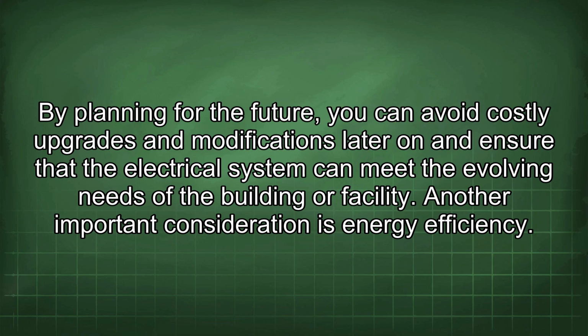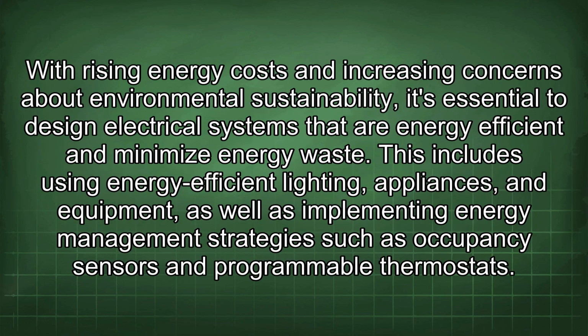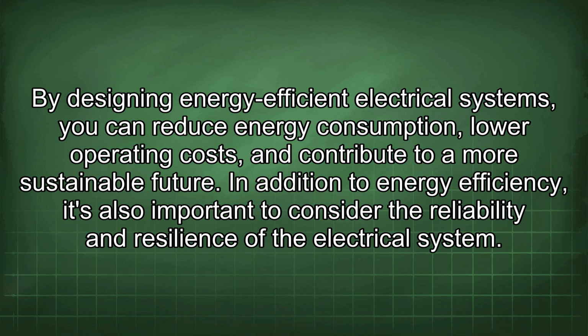Another important consideration is energy efficiency. With rising energy costs and increasing concerns about environmental sustainability, it's essential to design electrical systems that are energy efficient and minimize energy waste. This includes using energy-efficient lighting, appliances, and equipment, as well as implementing energy management strategies such as occupancy sensors and programmable thermostats. By designing energy-efficient electrical systems, you can reduce energy consumption, lower operating costs, and contribute to a more sustainable future.